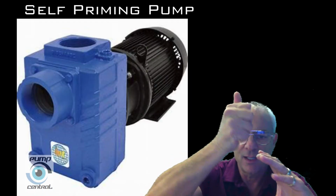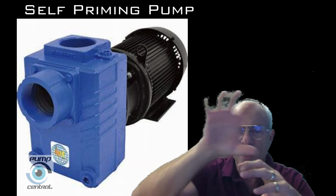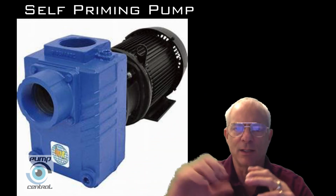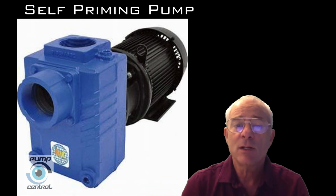Well, how do you get rid of that air? Well, you need somewhere for that air to rise up vertically and get off the impeller. So you have to create an area above the impeller. And when pumps are designed that way, they're called self-priming.